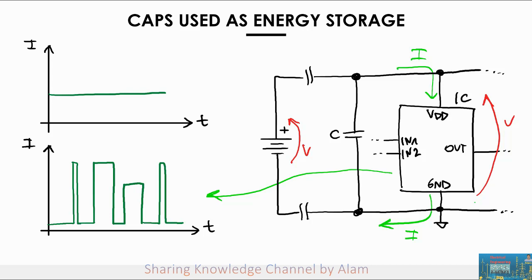In this case, the real explanation also involves the concept of inductance, but you can still think of it in the same terms. The charge needs some time to go from the battery to the device, and if the integrated circuit changes the request of current immediately, it will take some time for the power supply to provide the additional current required. So the presence of the capacitor as an energy storage, a charge storage, if you will, next to the integrated circuit can be very important because it can supply the additional charge that is required in moments of need.